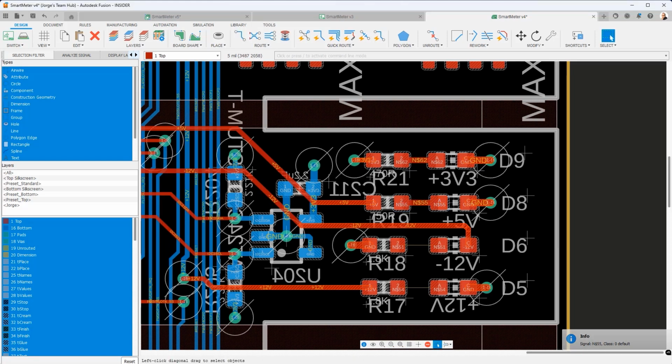Okay? So using the component groups, you now have another way to scope rules. So you could have multiple groups in a design and you can define individual widths for them. So for example, if you're routing a high density BGA, you may have a rule based on a group including the BGA and maybe any support circuitry that has very thin widths.